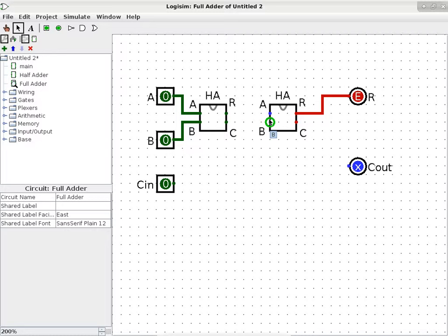When you look at the way we do the calculation in columns, you will understand that the result of the first half adder becomes a part of the input of the second one. Now, since addition is symmetric, I can connect that one to B. It would not be a problem. Okay. When you deal with a subtractor, it is no longer symmetric and it becomes important which one connects to A and which one connects to B. So this is just a reminder of your subtractor homework assignment. Okay, what about B? C in. B comes from C in, that's right.